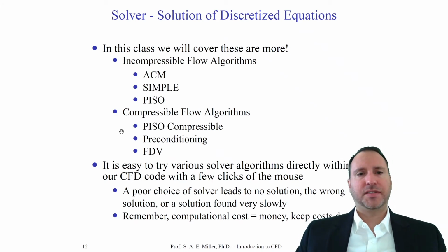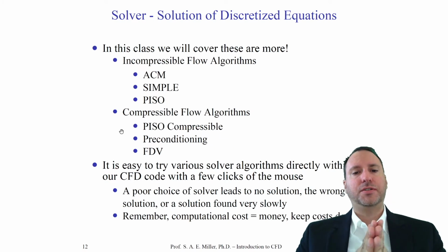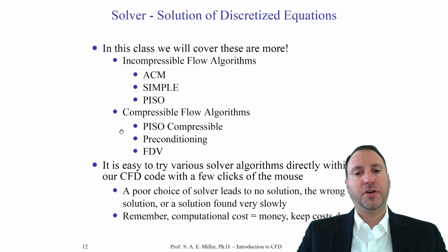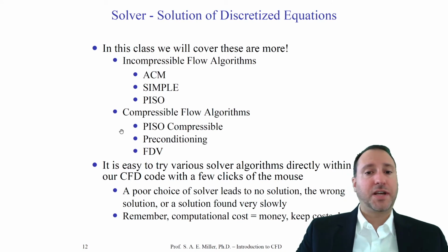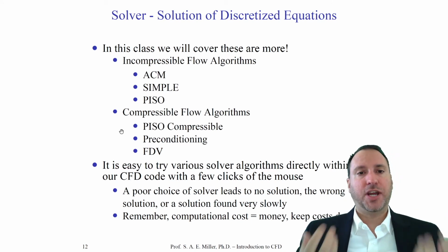The wonderful thing about CFD and some of these codes is these algorithms are integrated in solvers. So once you choose your set of equations like Euler or Navier-Stokes or some potential flow solver, you can change the solver and see how it affects the solution, or even if you get a solution or not. So with just a few clicks of a mouse or a few changes in a command line in your input text file for your solver, you can try these different algorithms.